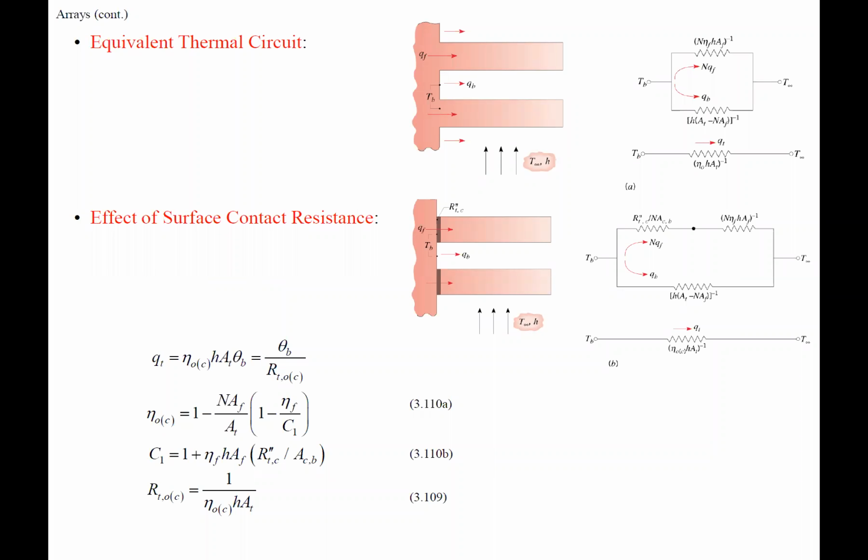All right, so I already kind of looked at this equivalent thermal circuit. That R_t,o, the overall one, is right here. It takes in the combined base and each fin, and you just look at it as a single resistor.